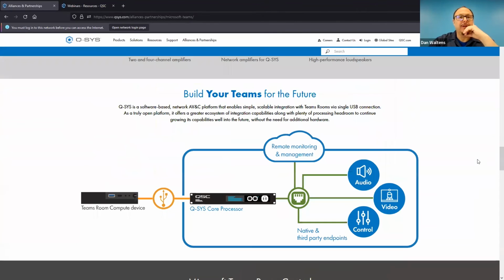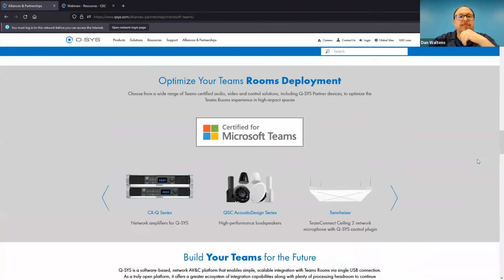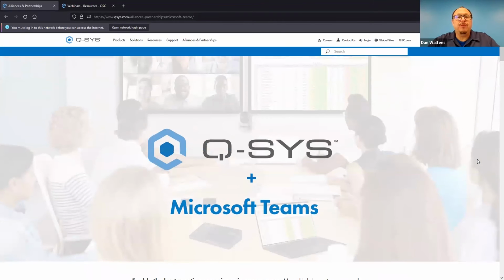So we've got one here from Zed Zakaria. How do you think you can drive the BYOM function? Is there any control to be added so that it's not confusing? Inside Q-SYS Designer, we do have some abilities to force a second page experience. We can also change the user interface that's on that tab. So when you're in a Teams room and you need second page control, you plug in, and you flip over to the second page, you would have it themed and look like Teams.